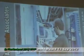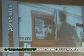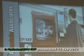When placed in the semi-automatic mode, the machine runs one cycle and then stops. The semi-automatic mode is used when parts need to be manually removed from the mold during the startup process and when troubleshooting defective parts. After the mold opens, the cycle stops. The operator then opens the safety gate, removes the part, and closes the gate.